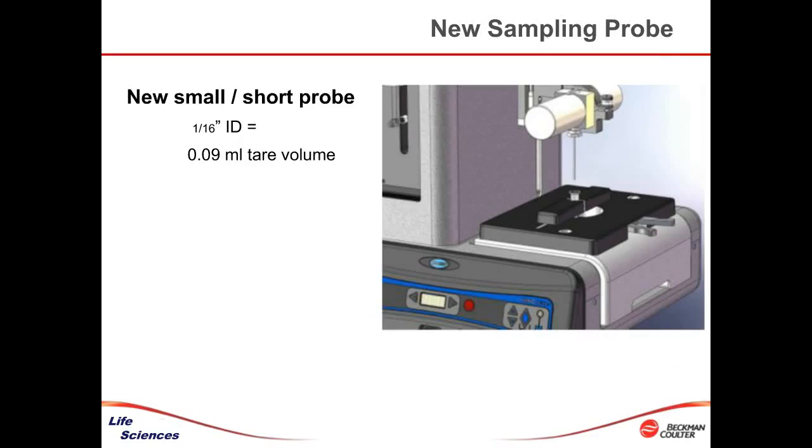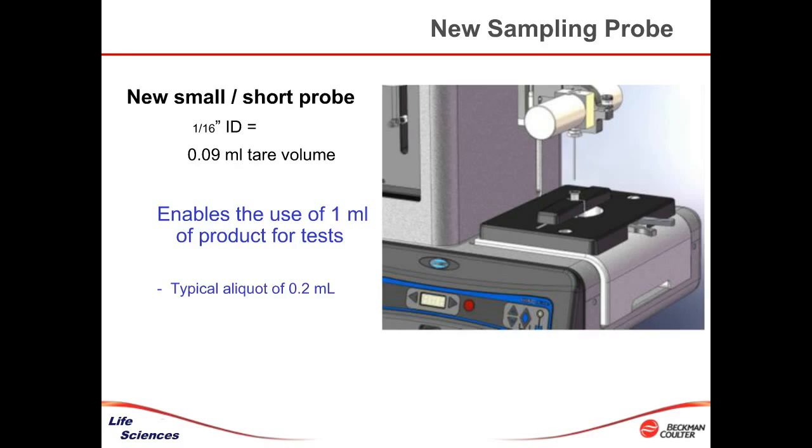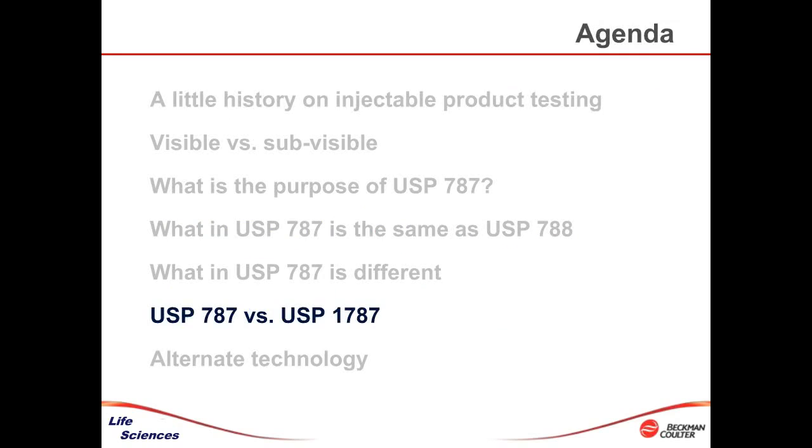So an additional aspect is, how do you minimize dead volume? How do you minimize the amount of material needed to initially wet or stimulate the sensor? So this allows like 1 milliliter of material to be used to do the 4 pulls of about 0.2 milliliters each. So various efforts were made to work toward small volumes and accurately sample very, very small amounts of material.